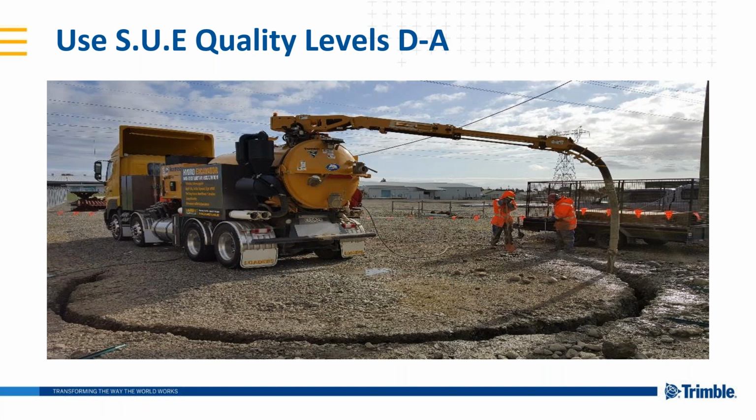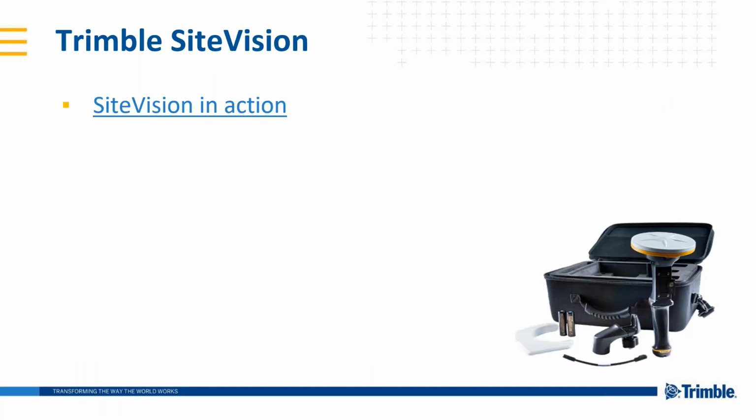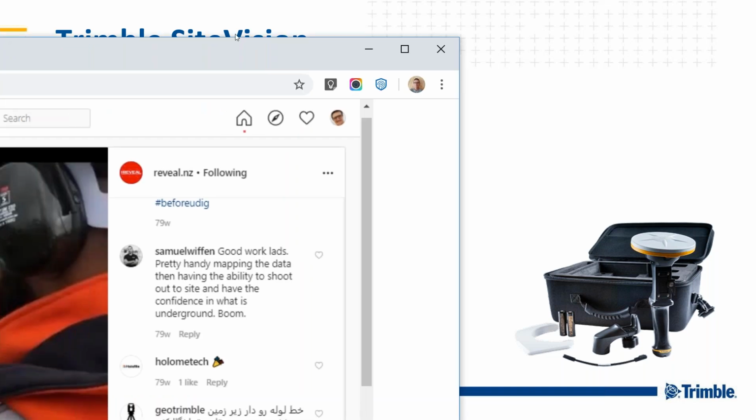Or you can get to what's known as potholing, which is, we assume and mark out an asset underground, and the only way to truly identify that that's exactly where that layer is, is to do a small dig to locate that service. And hopefully it's only a small dig and not requiring an extensive level of mining to locate the actual asset. And that would be the highest quality. So in their case, Jonathan, if you can actually just bring that Instagram video in.